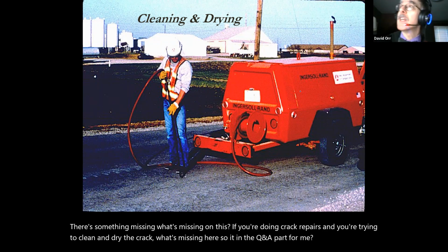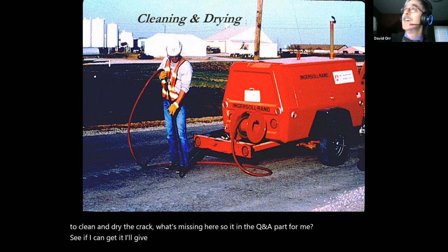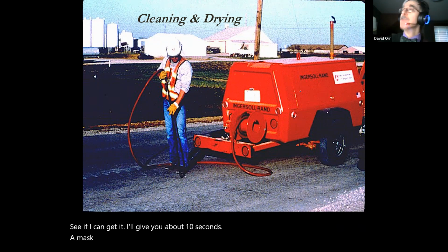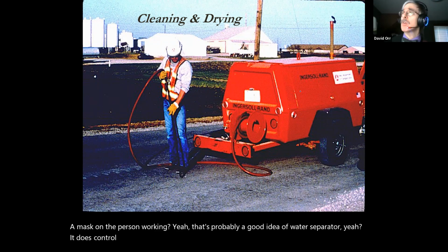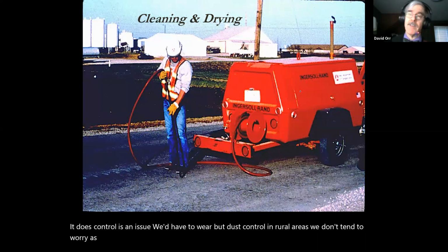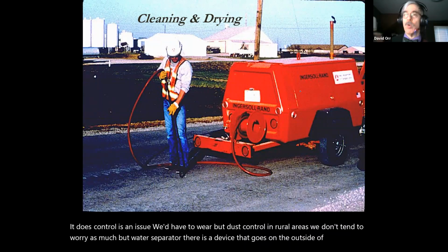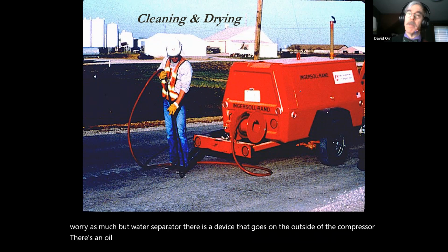See if everybody can get it. I'll give you about 10 seconds. A mask on the person working? Yeah, that's probably a good idea. A water separator. Yeah. Dust control is an issue. We'd have to worry about dust control. In rural areas, we don't tend to worry as much, but water separator. There is a device that goes on the outside of the compressor. There's an oil water separator. You don't want to be blowing water right into your crack.